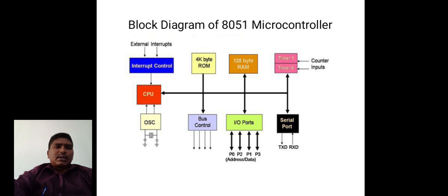The 4 kilobytes of memory has the address range 0000 hex to 0FFF hex, and the 128 bytes of RAM is used to hold the data.